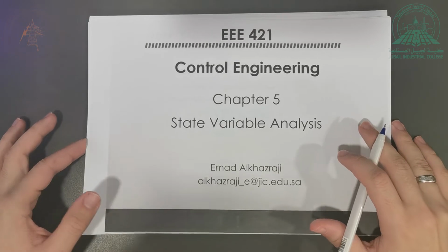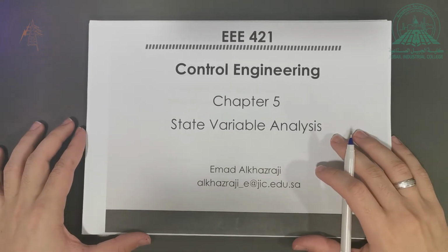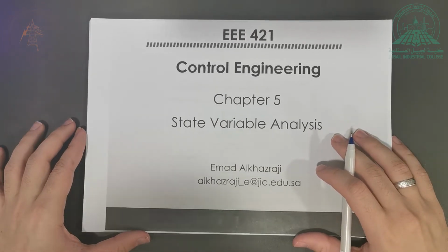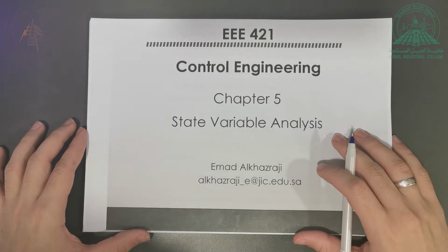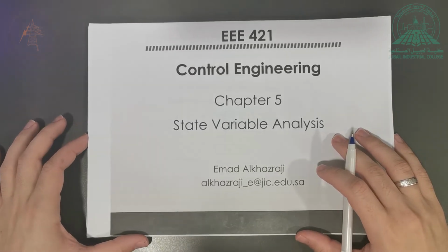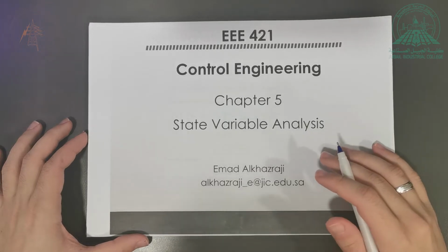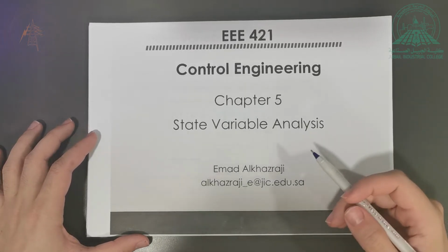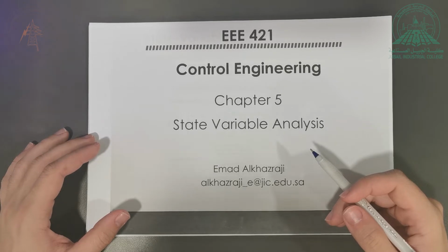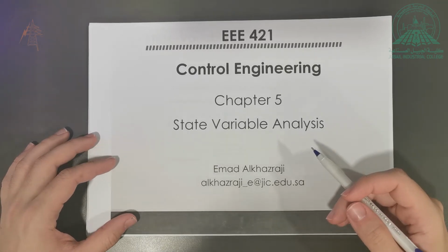We have seen how we can model an electrical circuit using the state space representation. Given any RLC circuit, depending on the number of the active components, we were able to come up with the number of states that are required in the circuit. Based on that, we used these states to come up with the state equations and the output equations. And based on them, we were able to extract the A, B, C, D matrices, which are used to model the system.